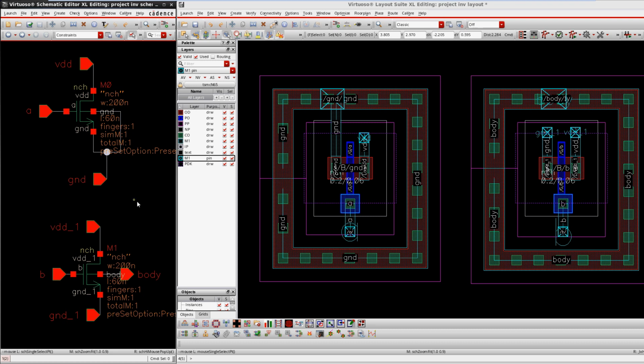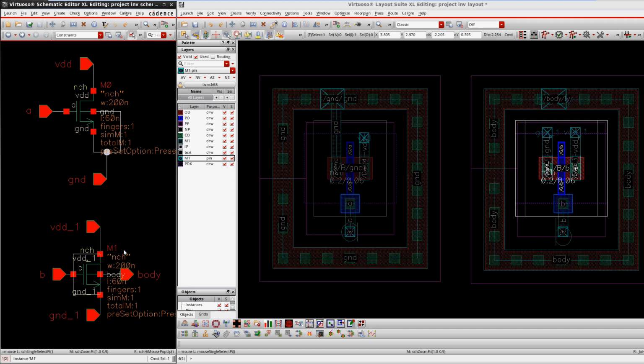But compulsorily we have to go for the DNW insertion, or deep Nwell insertion, in the case of M1. So the case of M1 is totally different, even if the device is not critical, even if the device is not creating any noise. Okay, this is a very pure and proper device which is not at all affecting any neighborhood devices.